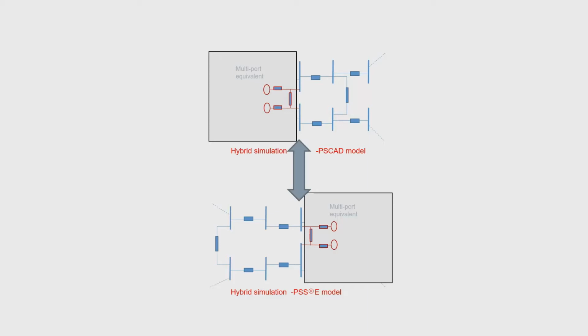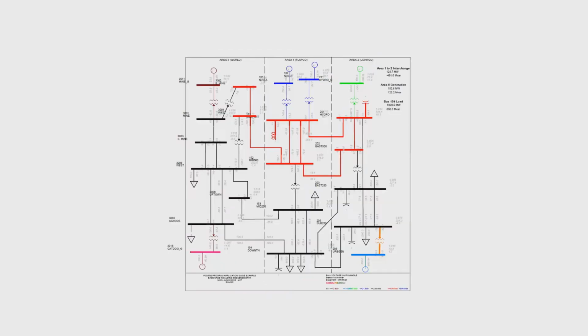The calculation of a multi-port network equivalent is based on the LDU reduction technique, which involves complex mathematical calculations. The E-TRAN tool can be effectively used to perform these tasks and to automate the co-simulation process. The simple Save NW case is used to demonstrate this. The raw file and DYR file are the required starting point and are available in the PSSE example folder.